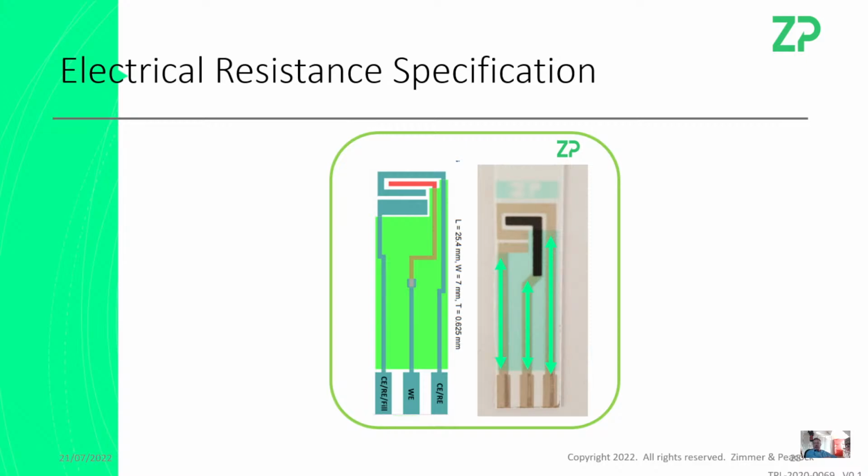If your conducting track is always 1 ohm, it's probably good to be generally in 1 ohm. In fact, I'd actually say that if the resistance is 1 to 10 ohms, you don't really care. And the reason I make that statement is because the biggest resistance in your circuits is through the solutions. So if the resistances along these tracks are less than some tens of ohms, you don't really care that much.